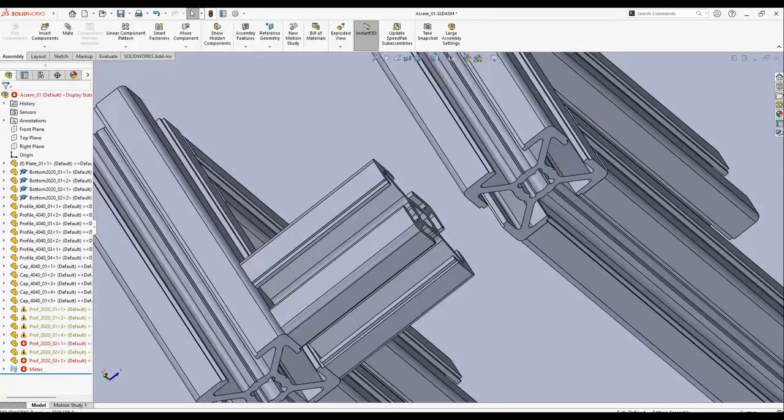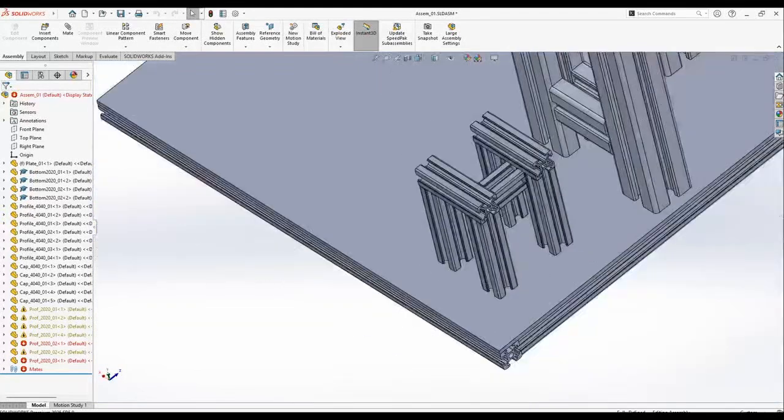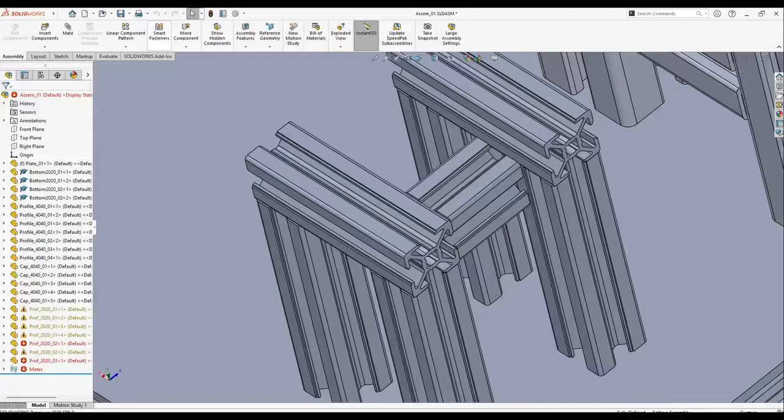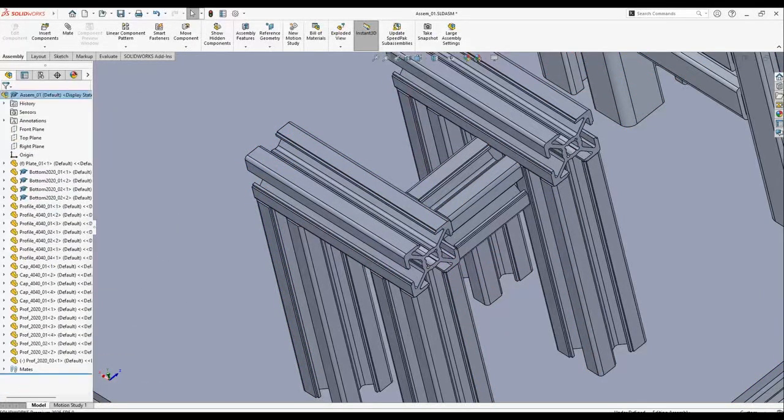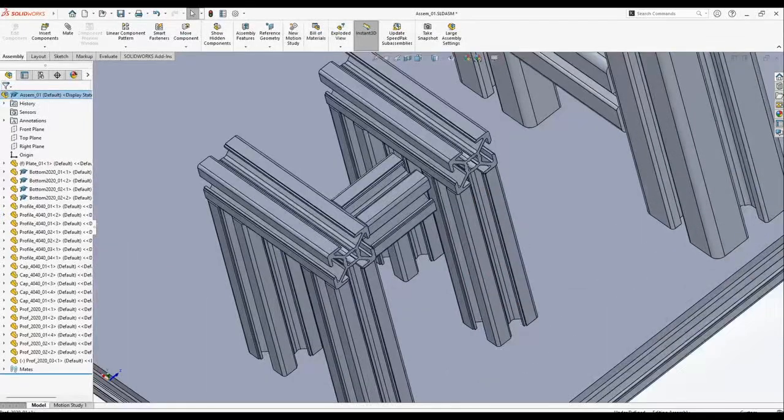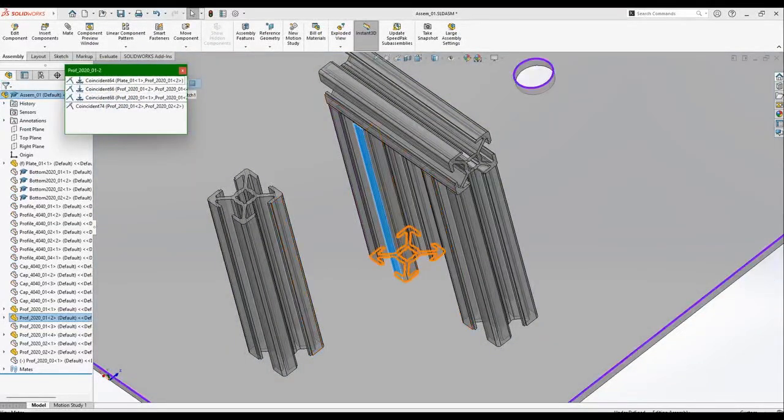Go back, and if you're rebuilding it, one more time maybe go back, so you don't have the possibility. Okay. Sometimes it happens that by saving you can't go back 2 times. Go again to the red one, delete it, and you don't have errors anymore, but the positioning is not good. What I need to do is open it and try to search. It means opening this part and checking the mates.